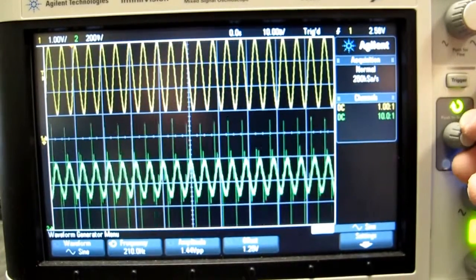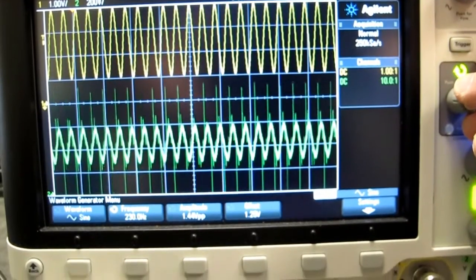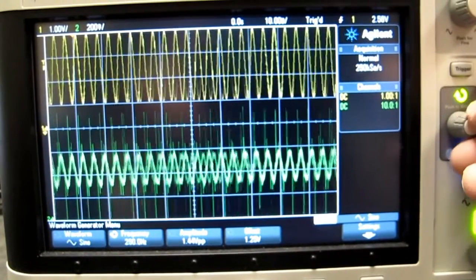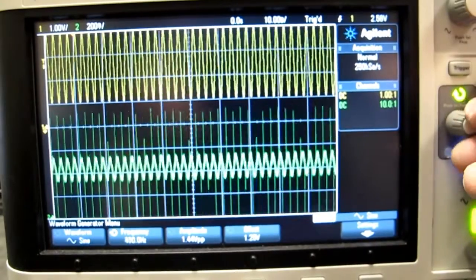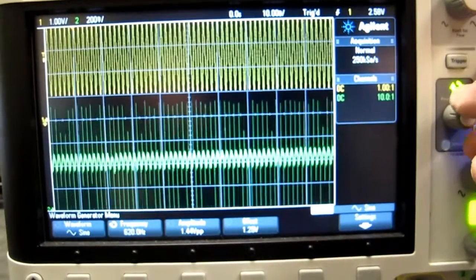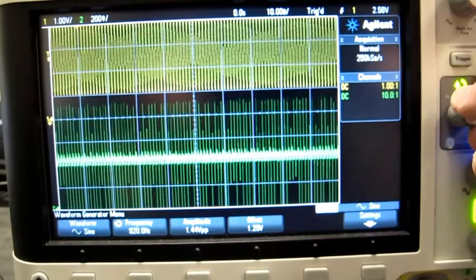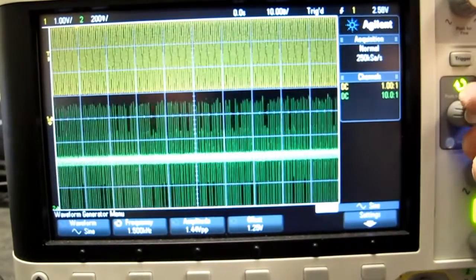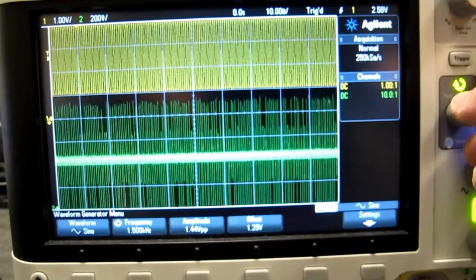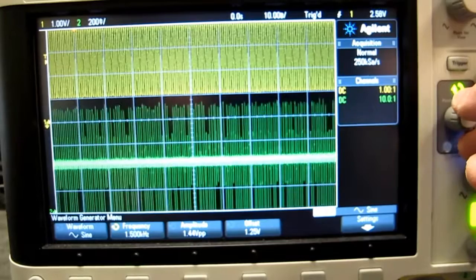now you can see the output decreasing. So ignore the glitches, just look at the output and you can see the output decreasing in size. If I keep on going up, you can see the frequency is increasing, looking at the top. Then it continues to decrease at the output, as it should. And eventually it essentially goes to 0 except for the glitches, which we could get rid of with a suitable analog low-pass filter on the D to A output.